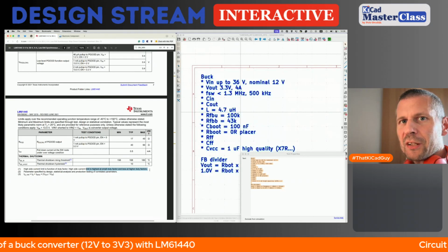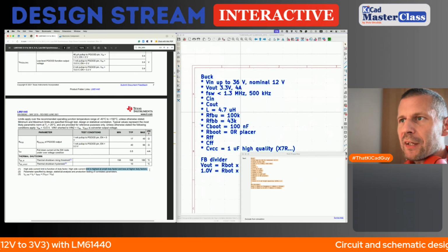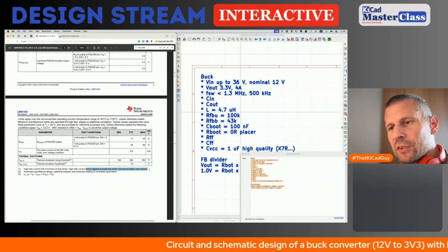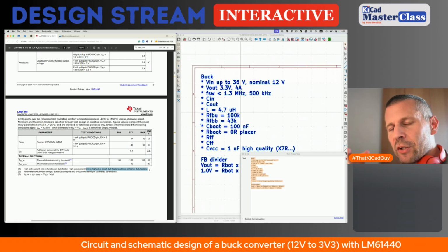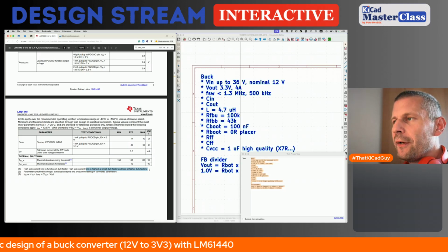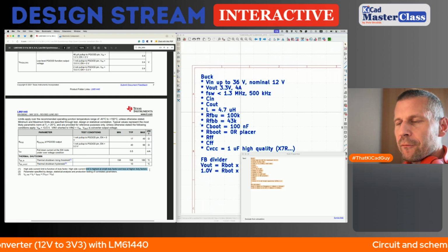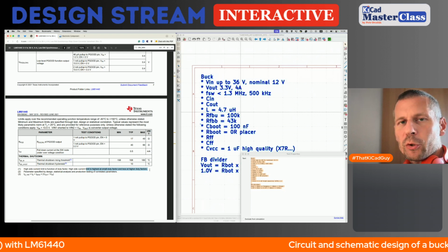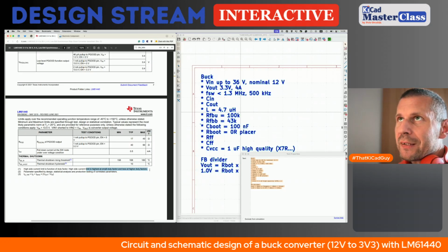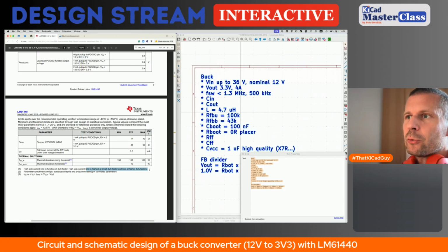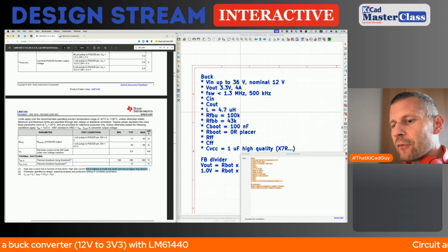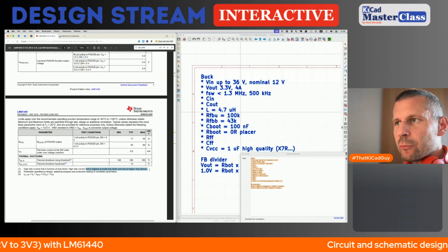big input voltage and small output voltage. It means that the high side switch is on for a very short period, and off for a much longer period. And when the voltages are almost similar, for instance for 12 volt input we will need, let's say, 11 volt at the output, the switcher is almost always on because the output is very close to the input voltage.